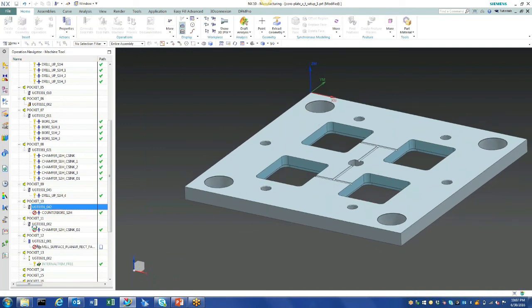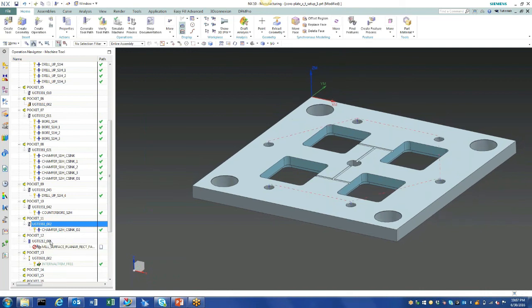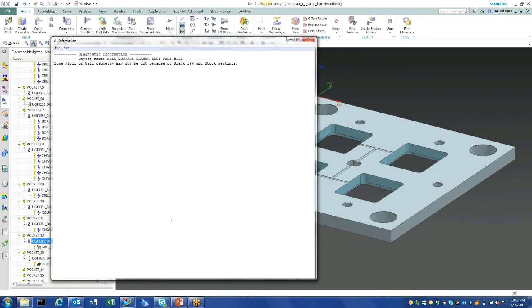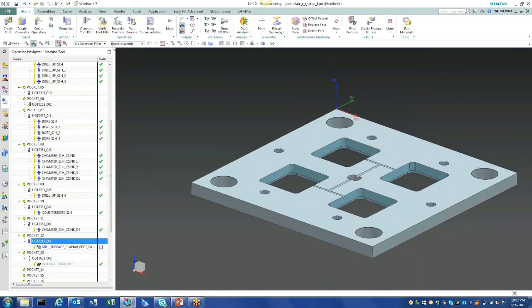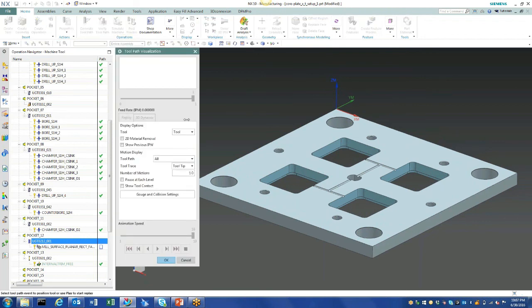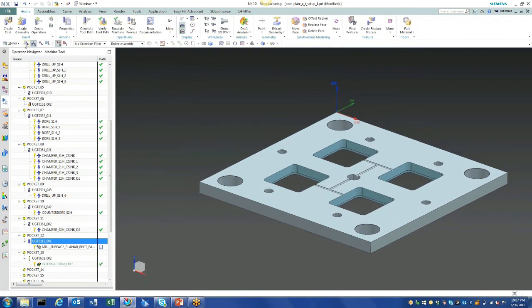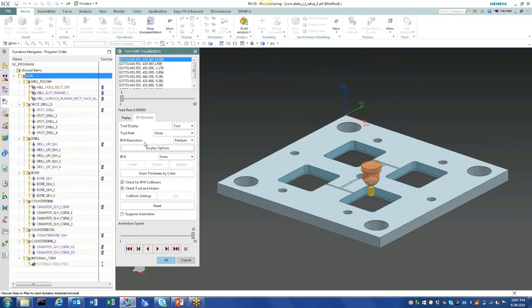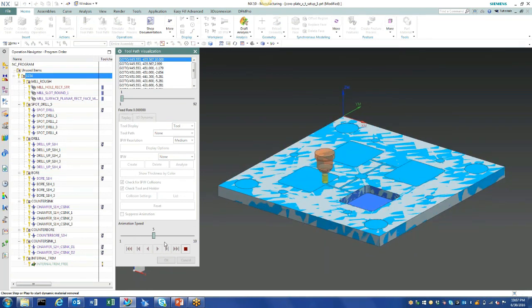And then after we have all these toolpaths generated, we're going to check out how NX handles feature-based manufacturing and how good of a job it does for you. This was an explanation of the operations, but if I was to actually program this, it would only take me 3 to 5 minutes to do that. We're going to choose 3D Dynamic. So you can see it's machining the pockets out down to the floor. And you remember I didn't select anything. All I selected was the part and told it to do the hard work.